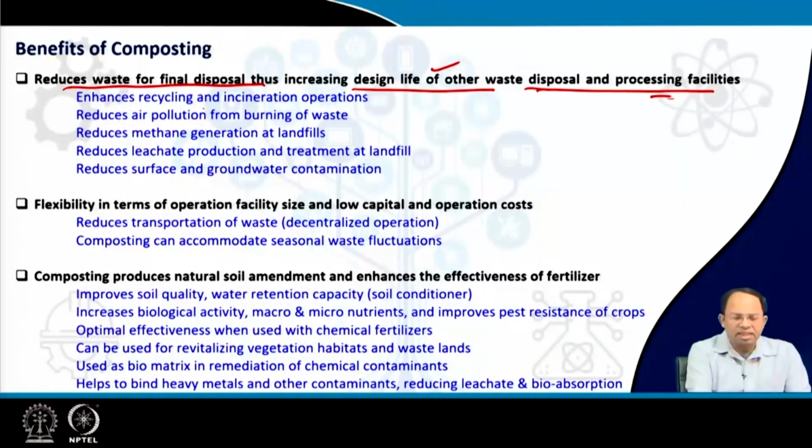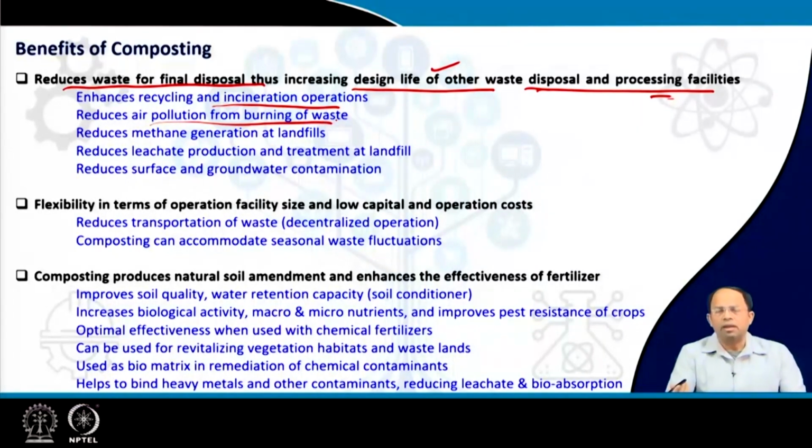It enhances recycling and incineration operations, which we discussed, and reduces air pollution from the burning of waste, because we are sending less waste for burning or incineration. The organic content is less, so automatically the air pollution would be less. It reduces methane gas generation at landfill. Organic waste is the reason why so much methane gas is produced in our landfill sites. So if I can take out the organic waste, automatically the methane gas generation would be lessened.